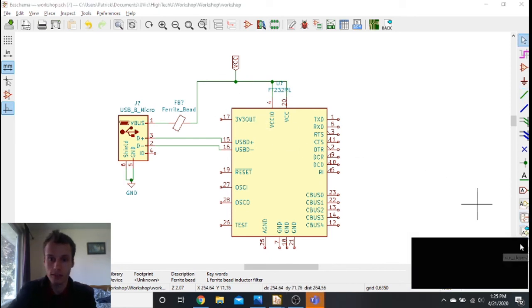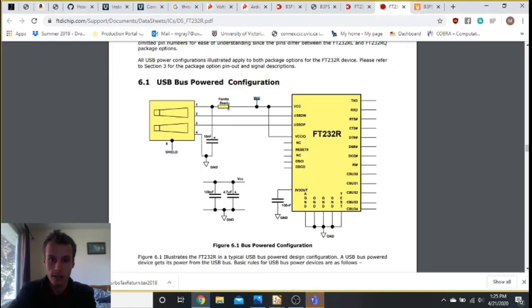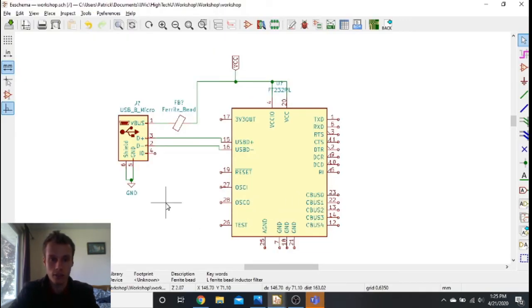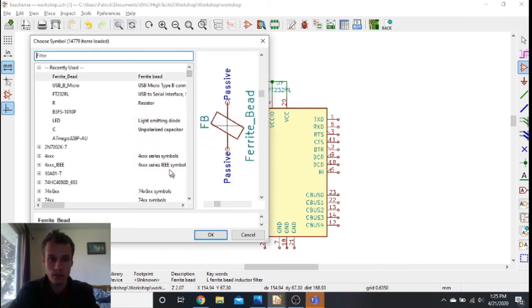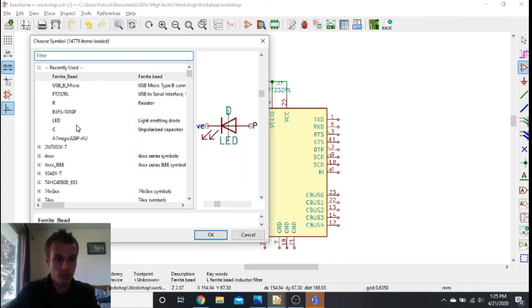So we do need a filter capacitor. We see here that there's this VCC and there are these two capacitors. We have a 100 nanofarad and a 4.7 UF capacitor, and these connect to the VCC here and to ground as filters. We also have a 100 nanofarad here. So let's add those. Those are also just to limit noise on the power line. So we have these capacitors.